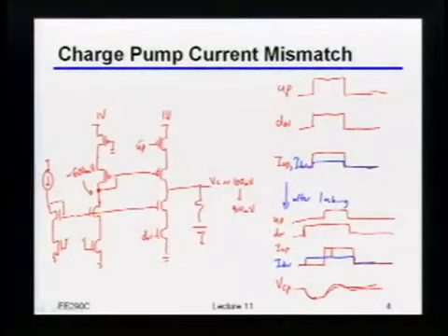The only reason that I was making different pulse widths was because I was trying to correct for some jitter in the first place. Here, even if there's absolutely no noise, I will create this glitch. So especially if the current mismatch is big, I could get a really big static phase offset, and then that reference spur will be proportional to that static phase offset and could be much larger than the noise I had in the first place.